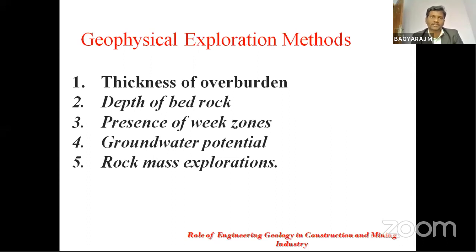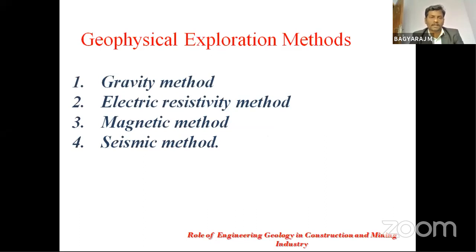We have different methods to use for exploration: gravity methods, electrical resistivity methods, magnetic methods, and seismic methods. We can use any of these methods, or different methods together, to get an idea of the deeper subsurface of the ground.